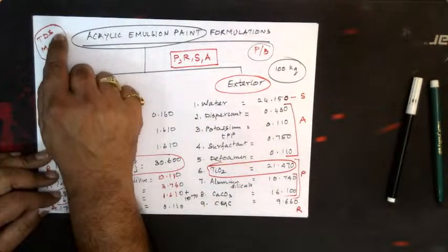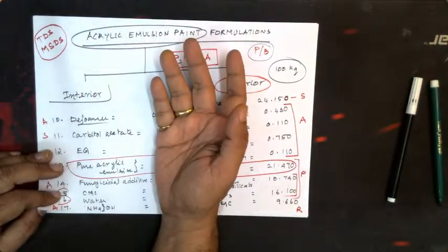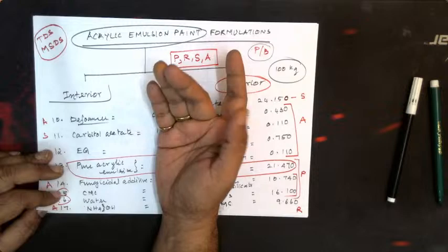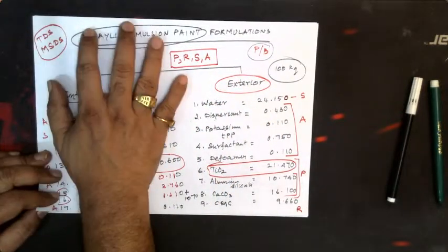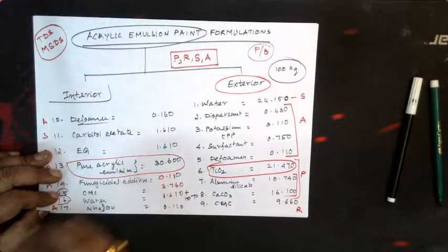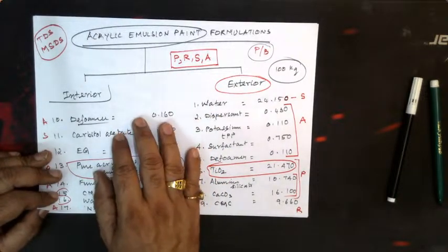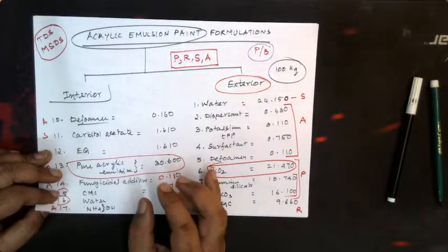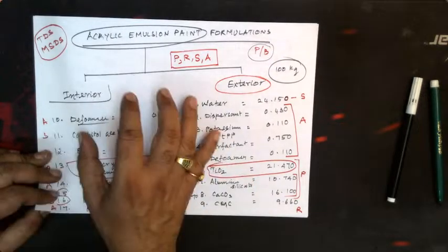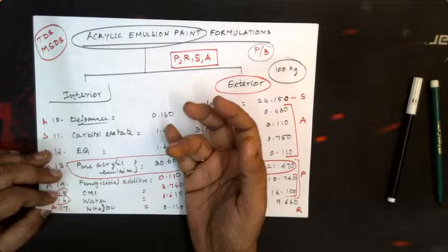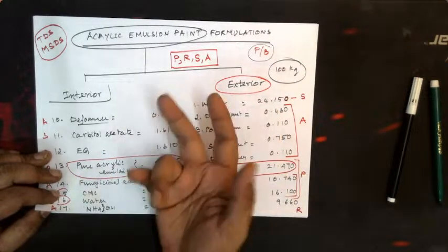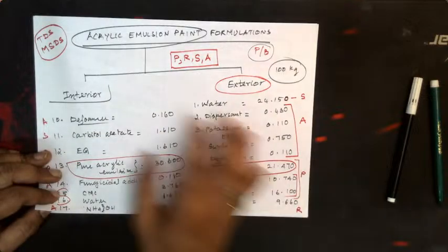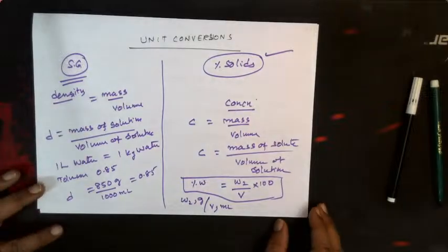And technical data sheet means, for example, if it is a liquid, you should have color, clarity, specific gravity, viscosity, all these parameters should be given. As far as the safety data sheet is concerned, it covers how it should be handled, how it should be stored, how your product should be filled, whether it is inflammable, whether it is environmentally friendly or not, and how to dispose of it. All these parameters are very, very important as far as the MSDS is concerned.